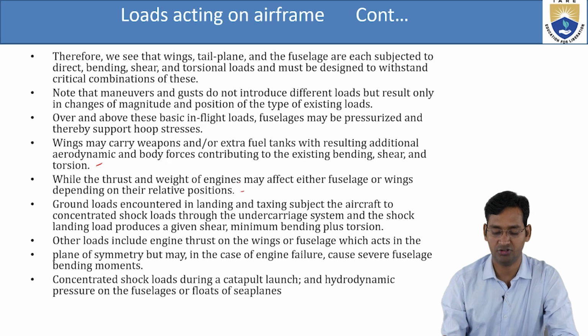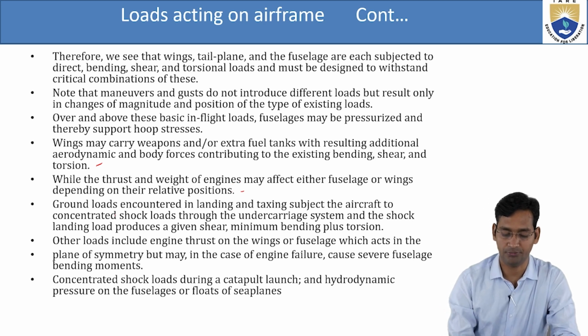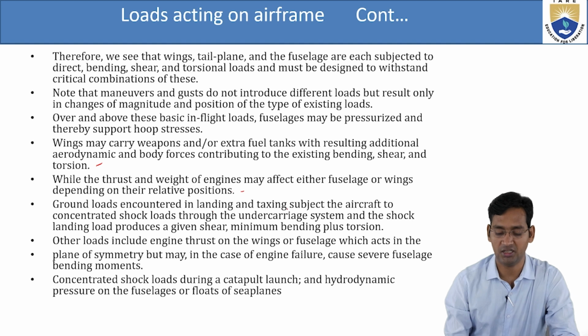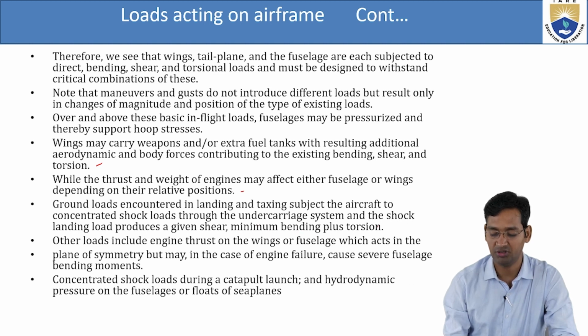Then there are ground loads encountered in landing and taxiing, such as the concentrated shock load, all through the undercarriage system, and the shock landing load produces a given shear, maximum bending moment and minimum bending moment plus torsion.